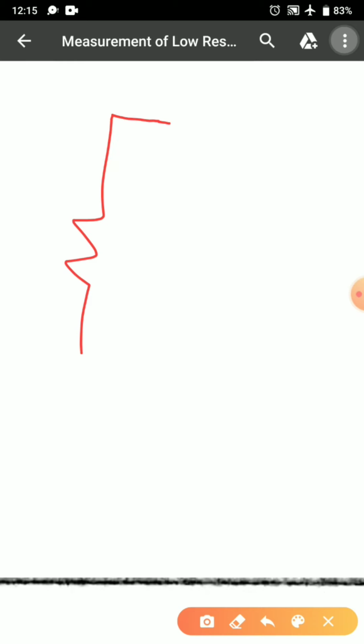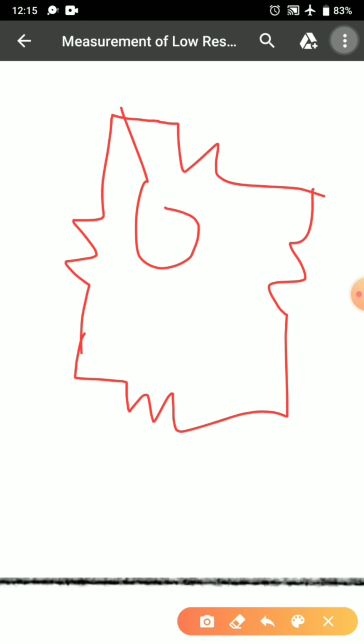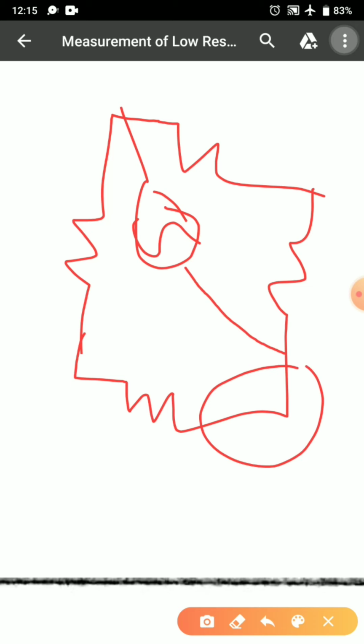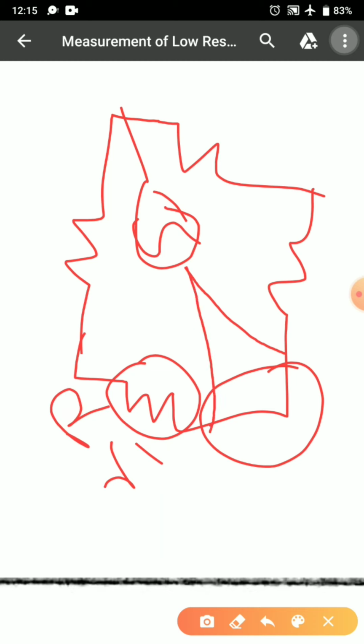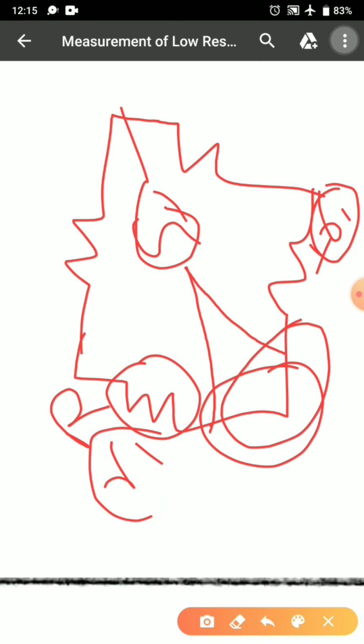This is the circuit diagram of a Wheatstone bridge. When we are talking about a Wheatstone bridge, the galvanometer will show null deflection. For example, if the galvanometer is connected here, what will happen? The additional resistance R1 will get added to the resistance R. Now if I am connecting the galvanometer here, what will happen? The extra lead that is connected here will get added to the resistance S1. In this manner, a small change in resistance will be felt in the measurements that we are taking.